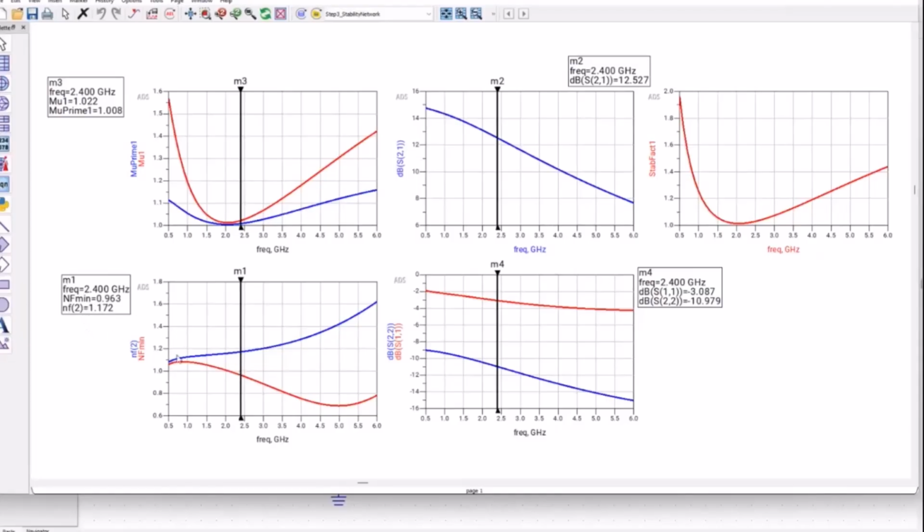As you can see right now, the NF minimum, which is the inherent noise figure, even if you do the best noise match to this LNA, you will be able to get 0.96 dB. So keep an eye on your target noise figure. Remember, right now there is no impedance matching network, there is no PCB loss, there is no transmission line. Basically, what you are seeing is just the inherent transistor with two or three components like resistor and capacitor.